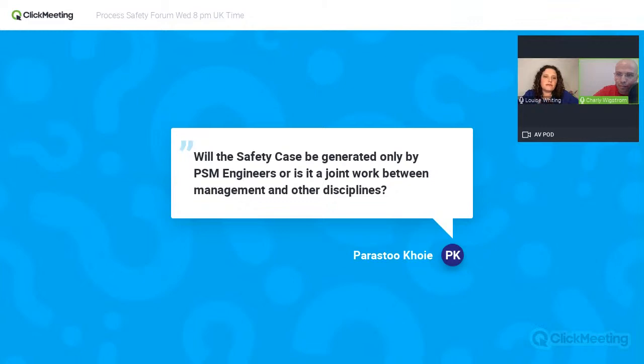Yeah. So I've developed a safety case, and although I did most of the work because I was the process safety engineer, it definitely needed the support of management, operations and the other engineers, because even some of the studies which support the safety case, for example, the cause and effects, the SIL study, the P&IDs, are all generated by other disciplines, not myself. And then also things like the risk-based inspection, or the RBI, is generated by another discipline. So all of that information needs to be coming forward, and then we need the operating practices, etc. That all needs to be filtering into the action plan for the safety case. And if you try and generate it on your own, you're not going to get a very useful document.